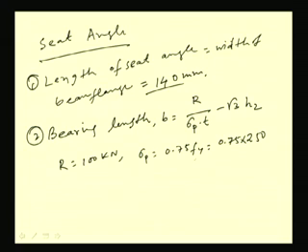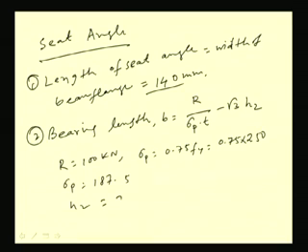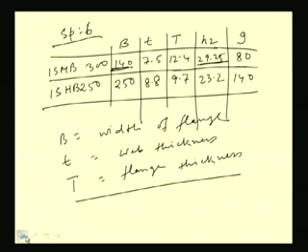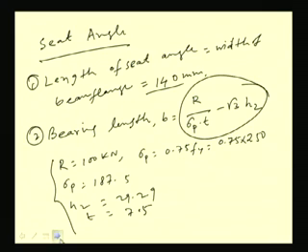If we consider Fy as 250, then sigma P will become 0.75 into 250, that is 187.5, and H2 is given as 29.25, and thickness t is given as 7.5.